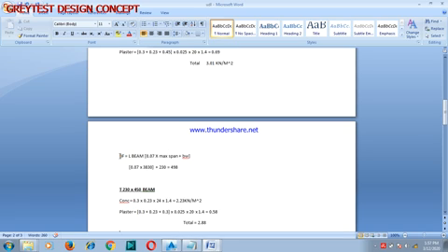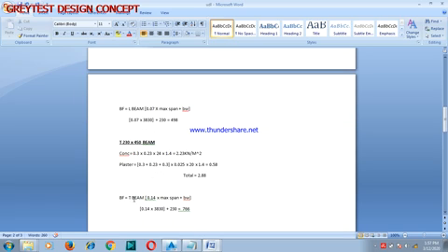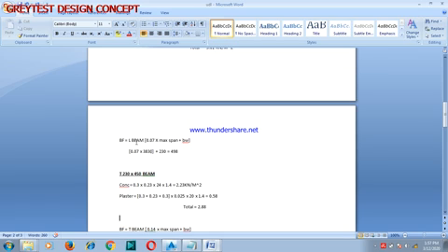Now, breadth of flange. We have breadth of flange for L beam, we have breadth of flange for T beam. The breadth of flange for an L beam is always 0.07 times the maximum span plus your breadth of web. Now 0.07 is actually gotten from a small formula.